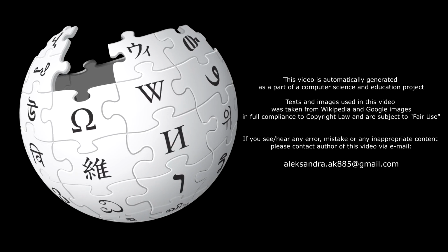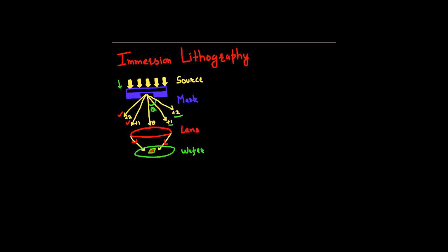Immersion lithography is a photolithography resolution enhancement technique for manufacturing integrated circuits (ICs) that replaces the usual air gap between the final lens and the wafer surface with a liquid medium that has a refractive index greater than 1. The resolution is increased by a factor equal to the refractive index of the liquid. Current immersion lithography tools use highly purified water for this liquid, achieving feature sizes below 45 nanometers.